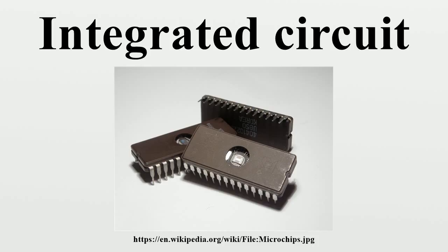A three-dimensional integrated circuit has 2 or more layers of active electronic components that are integrated both vertically and horizontally into a single circuit. Communication between layers uses on-die signaling, so power consumption is much lower than in equivalent separate circuits. Judicious use of short vertical wires can substantially reduce overall wire length for faster operation.